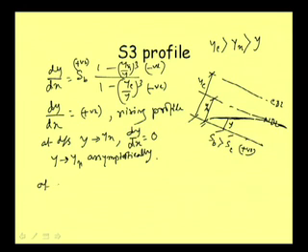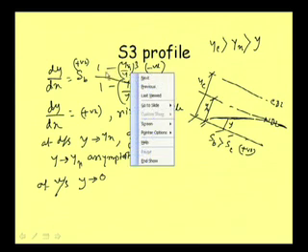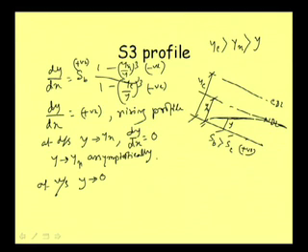And at upstream, what will happen? At upstream, again, if y approaches 0, then as per this expression, in the numerator yn by y becomes infinity and 1 minus infinity remains as minus infinity, and in the denominator also y is very small compared to yc, so this is also infinity, and finally, what we have is that dy/dx is equal to minus infinity by minus infinity, it is basically infinity by infinity.